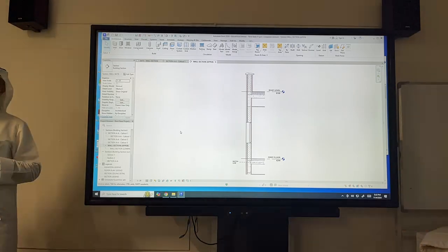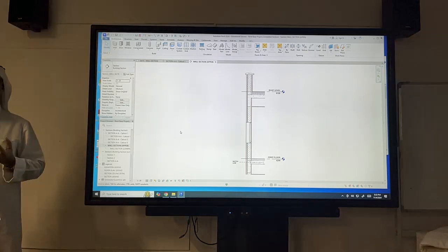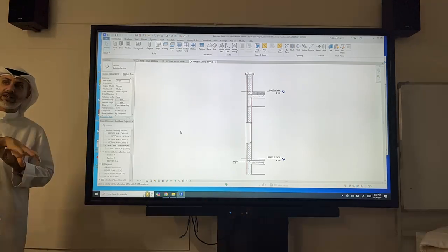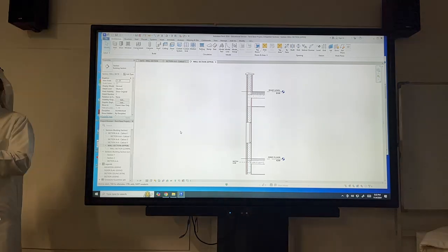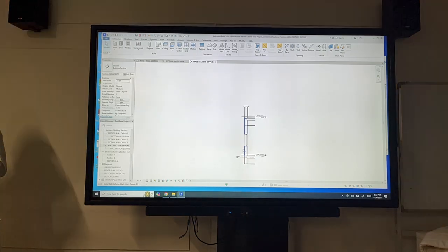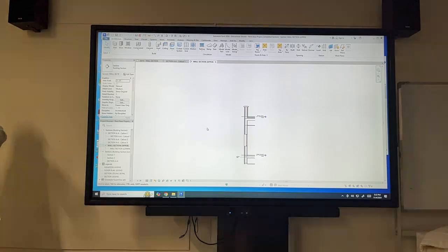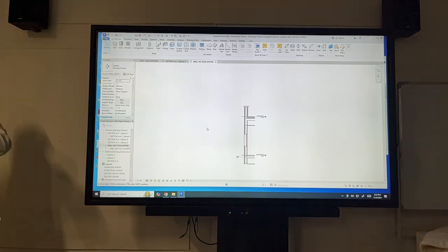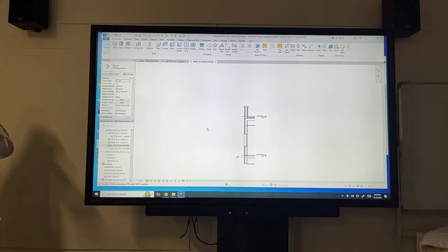So when we do callouts, by default, we're adding details that are not showing in the 1 to 50, but we're showing them in 1 to 25. But that would not be a dependent view. Otherwise, we'll have details in one of them and it'll be too busy in the other one. I usually do it when I have a very big building and I want to look at two wings on different sheets. That's when I want to see the same information, but maybe I can shift something in the text or I'm just looking at it on different sheets.